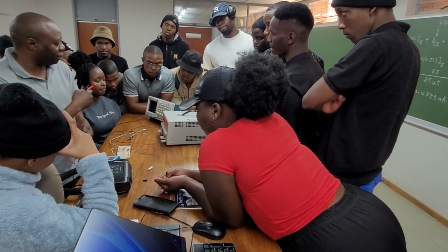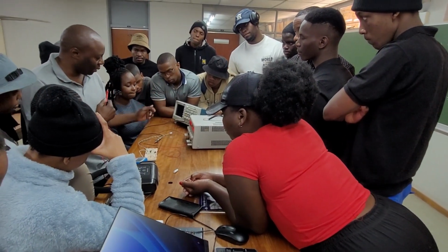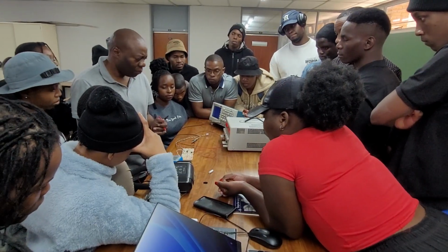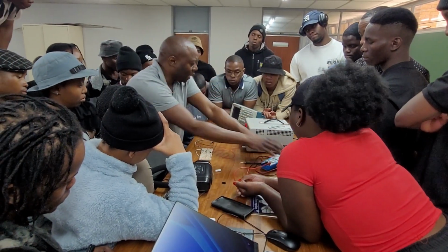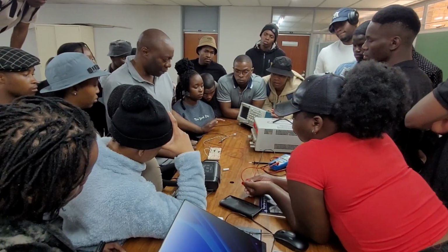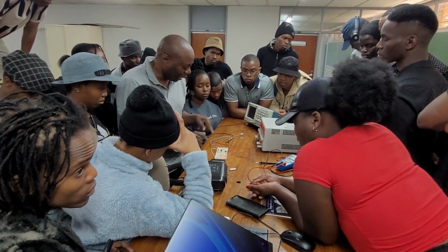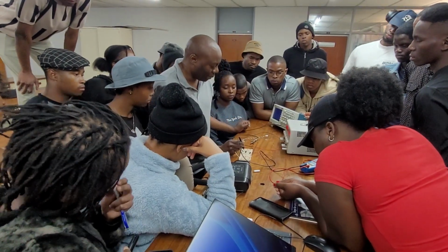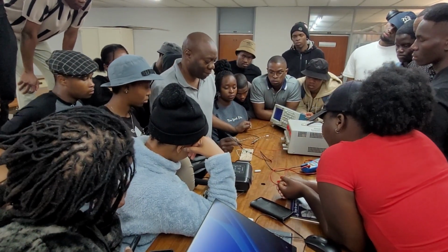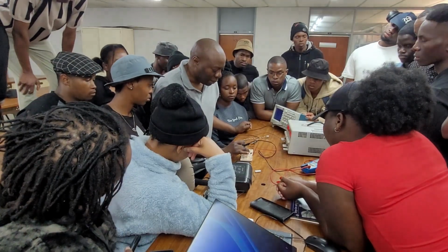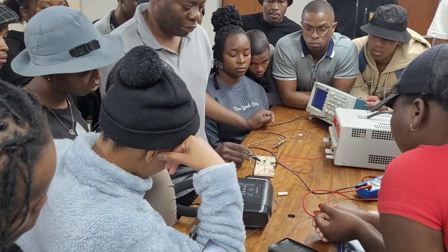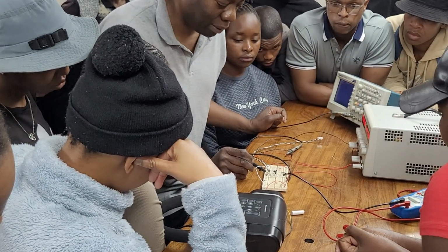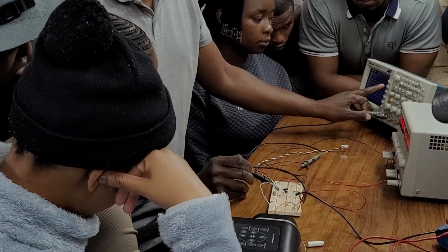Now this, I didn't really need to bring this, I just wanted to show you something. But the whole point of this is that this is actually an amplifier, okay, that takes a real input through this DC blocking capacitor, this one here. This is the input capacitor, that's the output capacitor. And you will see that I've loaded it with 1K for now. From that to the ground, there's a 1K resistor. Can you see that resistor? Yes. Okay. That, this one.